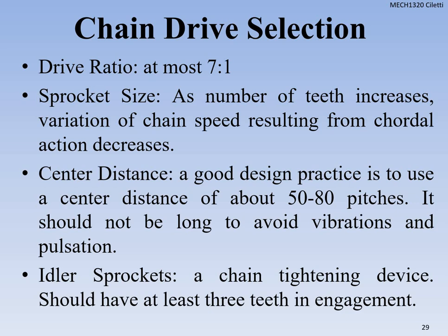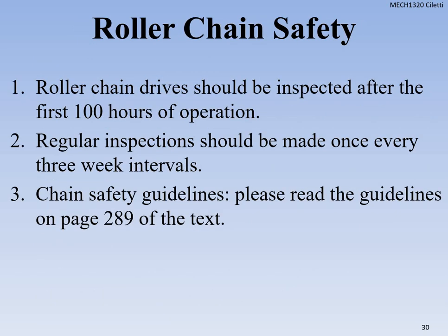Okay, so you don't want to have it too long or too short, also because of vibrations. Okay, sometimes we have an idler sprocket. It's a chain tightening device. This should have at least 3 teeth for engagement if we have an idler sprocket.